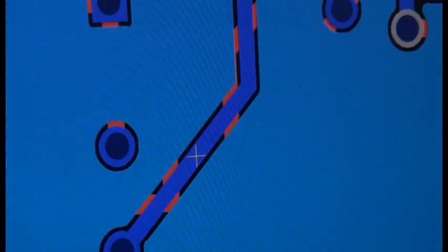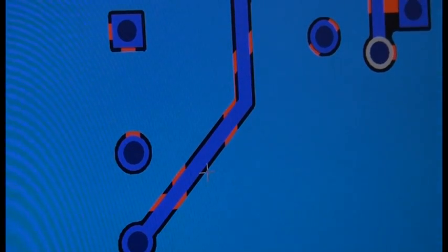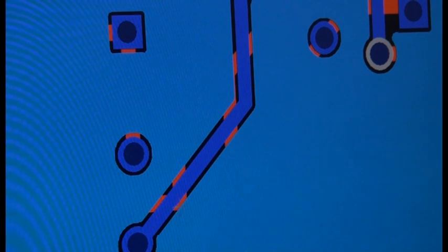And isolation, which is really this gap, or clearance is their term. The clearance is the thing that we just want to talk about. The main problem with this is that this clearance is too small, because when you come to try soldering that joint, you're only a quarter of a millimetre away from a ground.